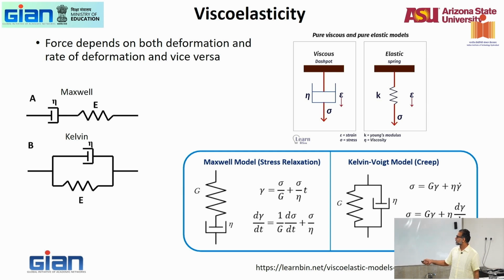When you put it this way, you can have the equations for shear strain and shear strain rate written as a function of shear modulus and stress. Shear modulus, stress, and viscosity and time. Right? So this is basically the elastic part, correct? Stress over shear modulus. That's your elastic part. And this is your viscous part, because viscosity is part of it. So that's your shear strain.